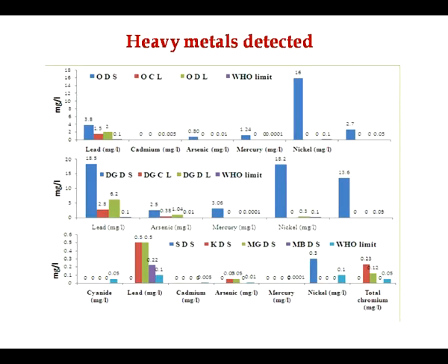And we have found, as you can see in the graph, that even heavy metals are leaching down. In the Ajmeri Gate area, a lot of lead concentration has been found, and when we explored the reason, there are many lead battery dismantling factories there. We found chromium, we found nickel, and also mercury in the groundwater. And Sushmita, when these chemicals leach down to the groundwater, it is not easy to treat and purify it. You can still think of purifying the river, but how about the groundwater profile?